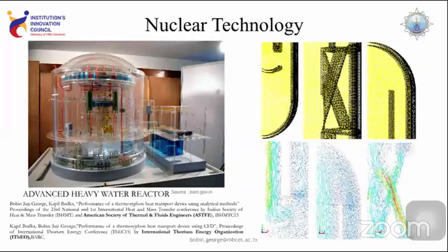Now, this is another project that I have worked on. On the left-hand side, it shows the advanced heavy water reactor, the research reactor being developed by the Bhabha Atomic Research Centre in India. I was there for one year as project training, and I was able to study a thermosiphon system. A thermosiphon is nothing but, instead of having a forced system to remove the heat, you use the density difference of the fluid itself to carry out the heat.